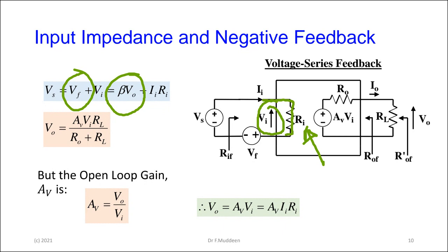We also know that at the output side, Vo is Av, you remember it's a Thevenin equivalent, so the output voltage now is a voltage gain times Vin, right? And our output voltage is being measured across that point. So we have a little divider with Ro and RL. So Av times Vin appears across this. So the actual voltage here is a little voltage divider arrangement with RL over Ro plus RL. Yeah?